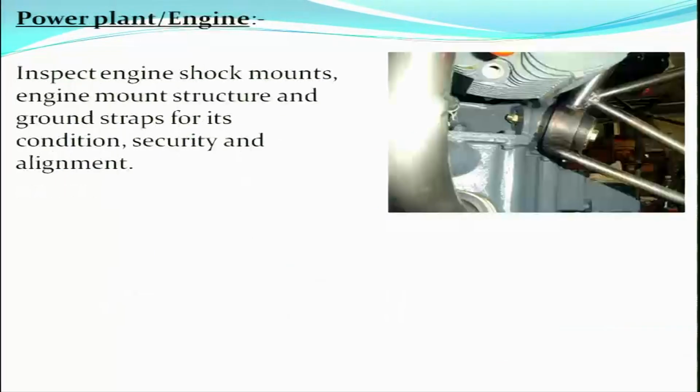Inspect engine shock mounts, engine mount structure and ground straps for its condition, security and alignment. So, in the engine mounting, the rubber shock mounts are inspected. The shock mount structure is checked for any damage, for condition, security and alignment.